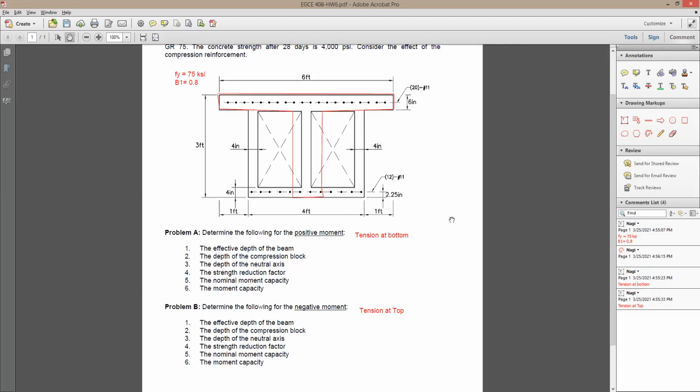Make it into a T-beam. Yeah, exactly. It is a T-beam. Very good. Right. It's like this. If here's some bottom reinforcing, it doesn't matter if it's going to be distributed or just concentrated here. Just a T-beam. And now, after you're done with this, because you're doing here the positive moment, you can do it exactly the same way. And you say, this now again is going to be my T-beam. It's going to be something like this, right?